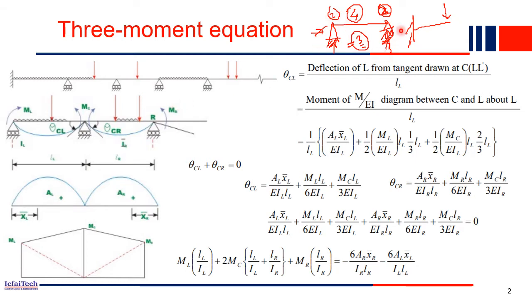So for example, if you consider this beam, this end is hinge, this end is also hinge, right? So you have two unknowns here, here also two unknowns. So four unknowns you have and three equations. So three unknowns you can compute using the equilibrium equations. But one extra additional unknown will be there, for which you have to employ the compatibility condition of this beam. So if you can write one compatibility condition for this beam, then we can solve the additional unknown.